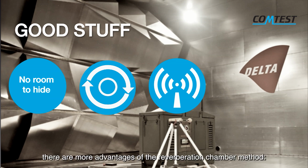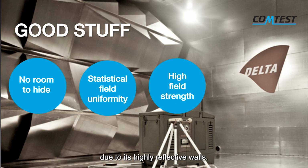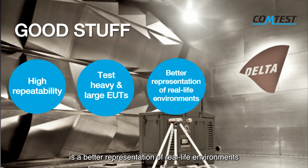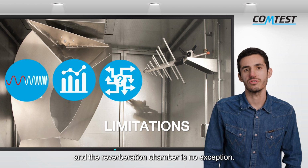Aside from that, there are more advantages of the reverberation chamber method. Statistically uniform field, its ability to generate high electric fields with moderate input power due to its highly reflective walls, high test reproducibility and repeatability, ability to house and test large AUTs, and last but not least, the reverberation chamber is a better representation of real-life environments, thanks to its nature of illuminating the AUT from various angles, polarizations, and orientations. Of course, every test method has its limitation, and reverberation chamber is no exception.